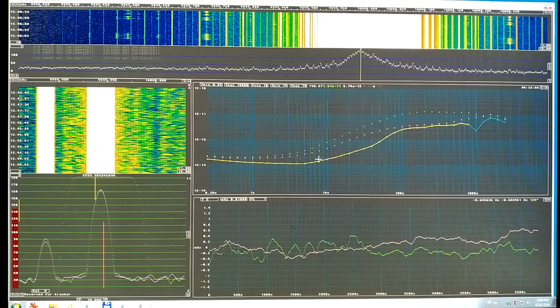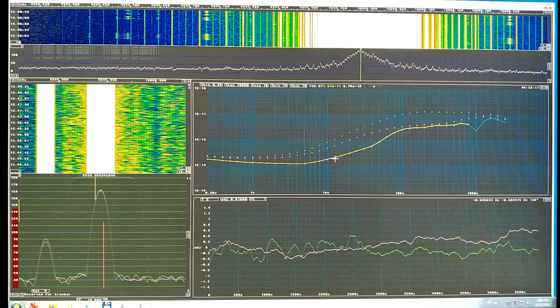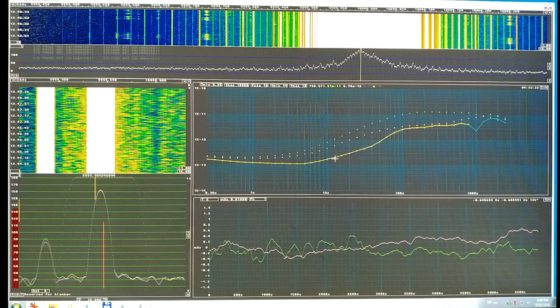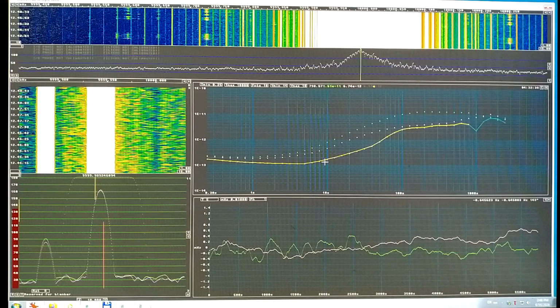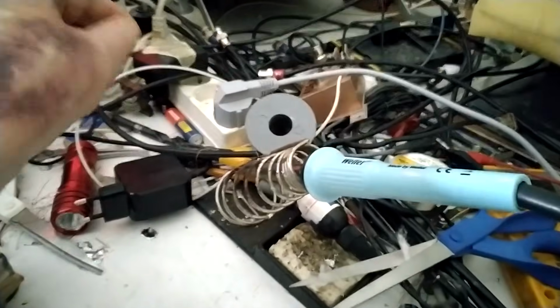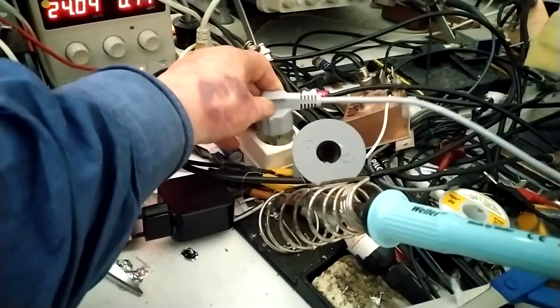And one more thing, I think there was noise from the phase lock itself that contributed to the high noise level at 10 seconds, or even below. I don't remember exactly, but there was some noise in this region that is now not present anymore. And noise from the PLL circuit, it's a CMOS thing, may have reached the oscillators, but now with that big resistor, frequency components at 0.1 Hertz can no longer come through.